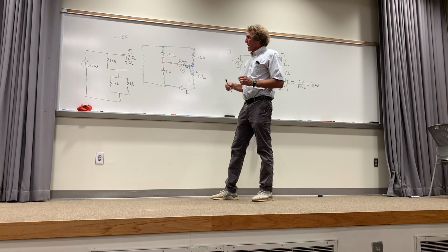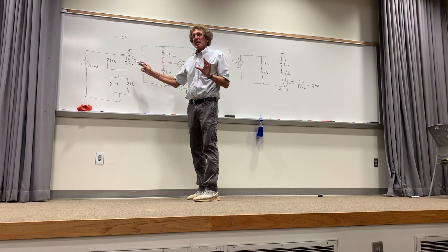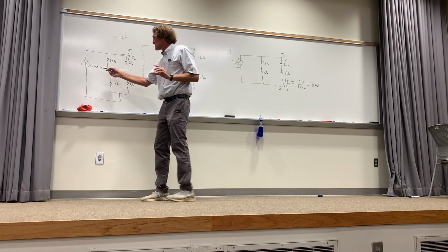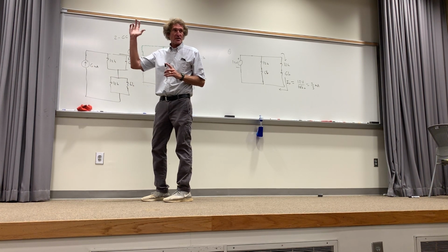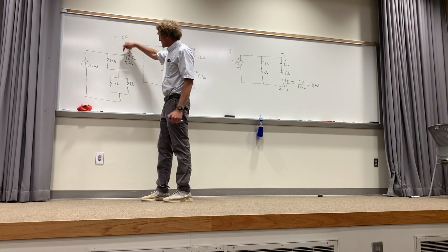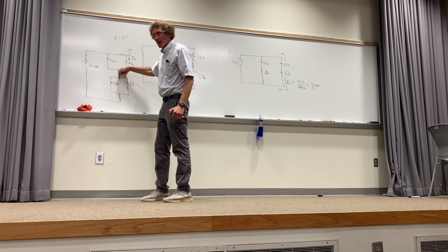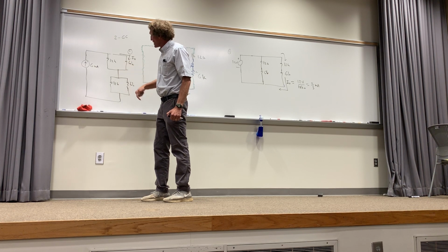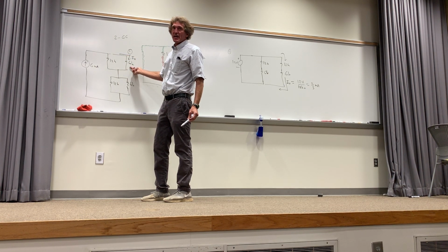Now, follow me. How much current flows down this 6K? Now think about this. Doesn't all the 6 milliamps flow through both of these two resistors? How many see that, class? Y'all see it has to, right? It's flowing there, some flows there, some flows there, but it all has to come together and flow that way, right? That's 6 milliamps going there, there's 6 milliamps. So couldn't I use simple current division to get that value of I naught, class?